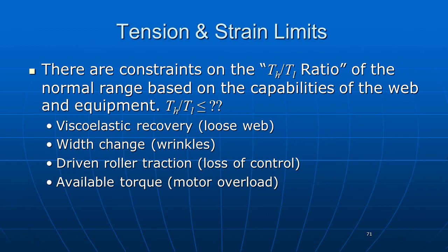Now, going back to the viscoelasticity, my typical experience with webs is they can instantly do about a 6-to-1 recovery. And so you don't want to design right at the limit of failure. And so I typically say take a tension drop no bigger than about 3-to-1. Give yourself a 2-times safety factor here. Your webs may be different, don't know.